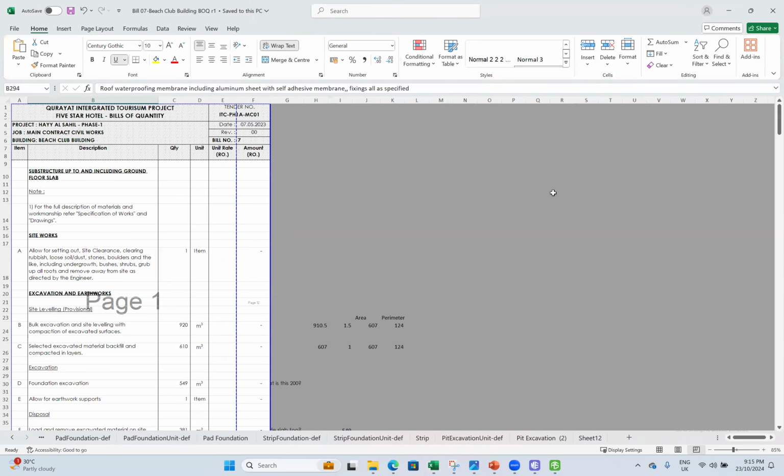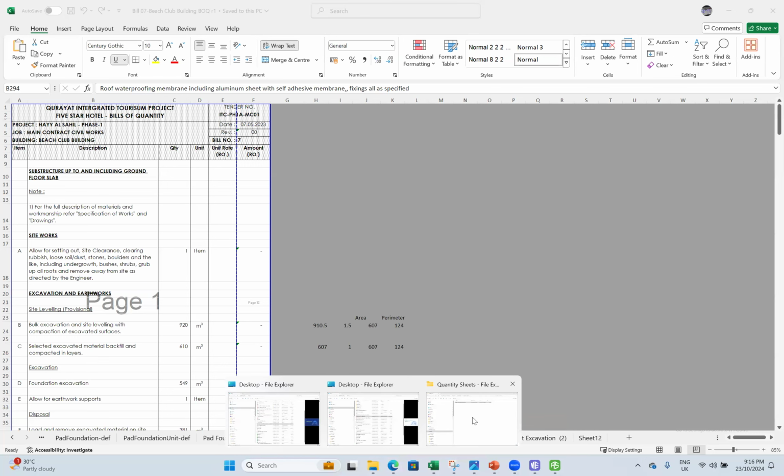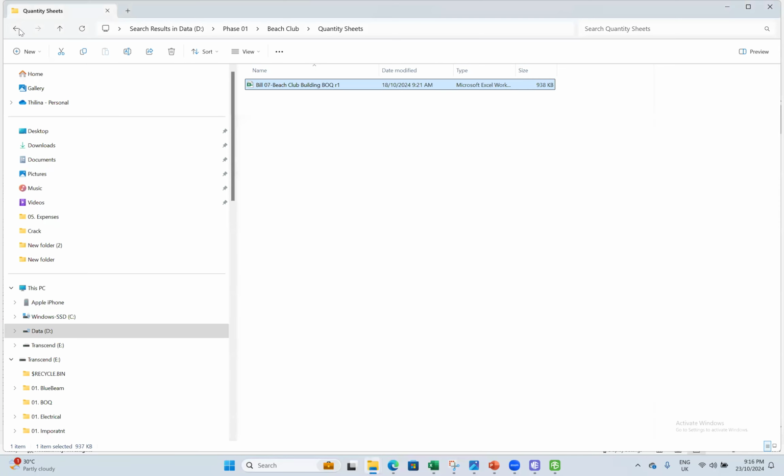First you have to read the drawing. You can observe whether they are in correct layers. If they are in correct layers, you can use the auto identification function and complete the model in a few minutes. If they haven't used any layers, you can use the manual method and create the 3D model. No issue. I will show you this project. Then you will be motivated to learn and earn from this technology.